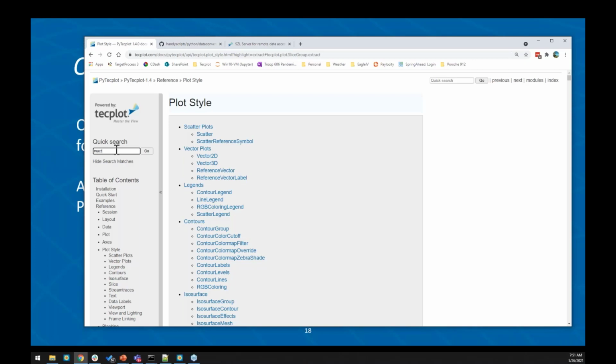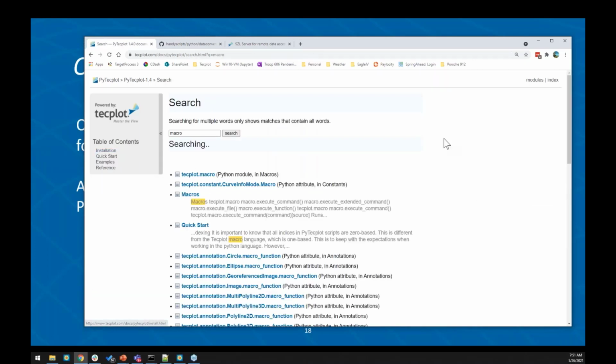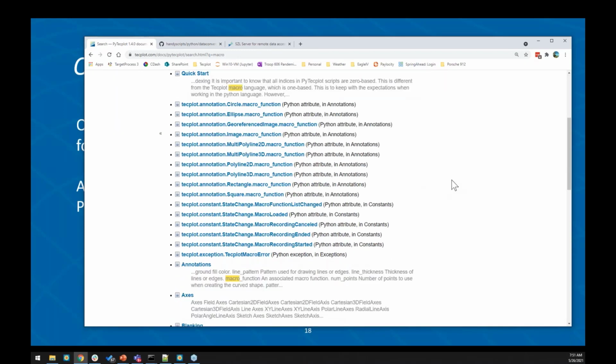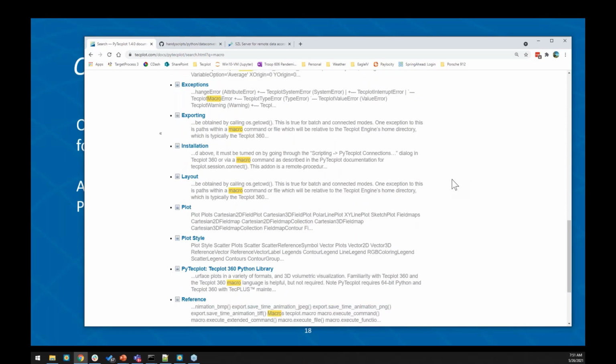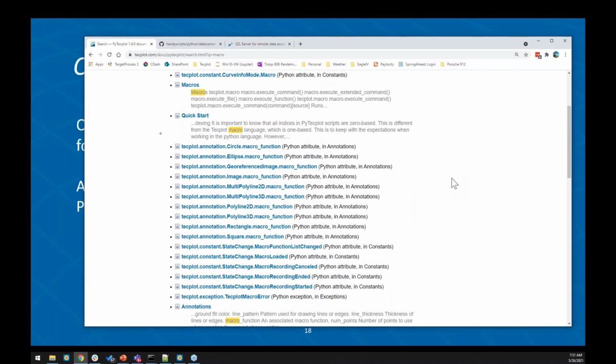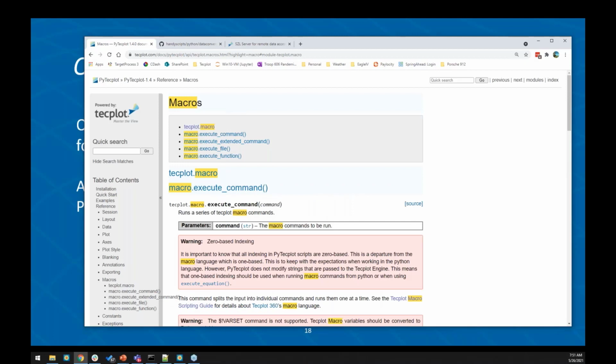Or another idea, maybe if you are thinking a little bit more Pythonic, what you could do is to load a macro into your macro debugger, and then you record a Python script. And if you then go step by step through the macro, then all the commands are converted to a Python script. I think this is a pretty attractive way too, if you are interested more in a Pythonic style to work with that.